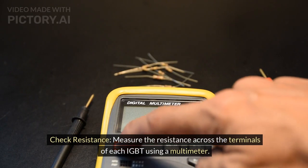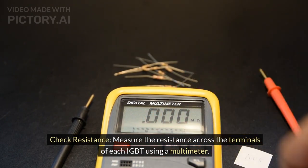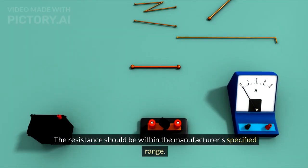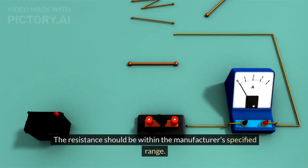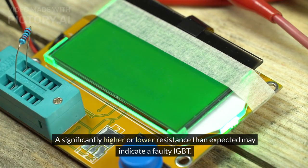Check resistance. Measure the resistance across the terminals of each IGBT using a multimeter. The resistance should be within the manufacturer's specified range. A significantly higher or lower resistance than expected may indicate a faulty IGBT.